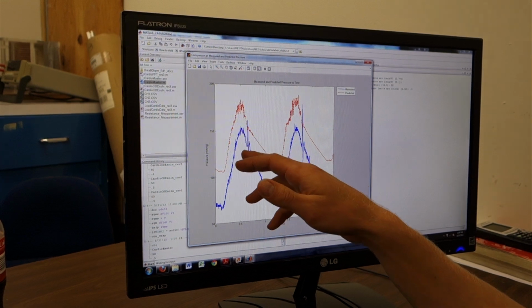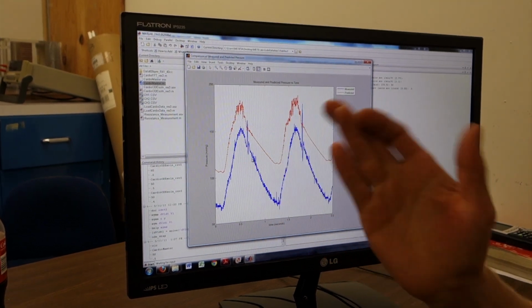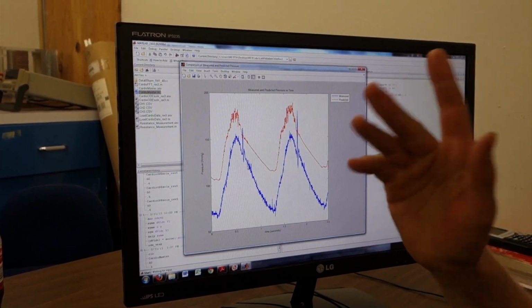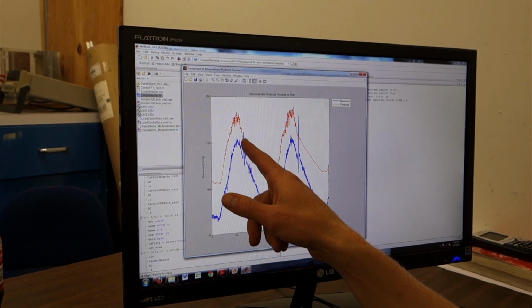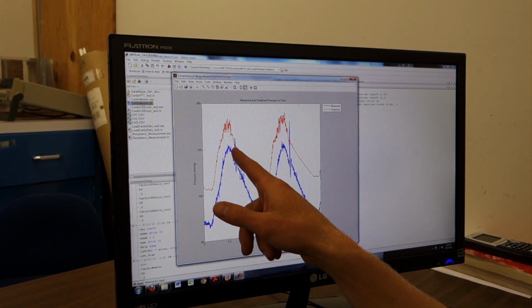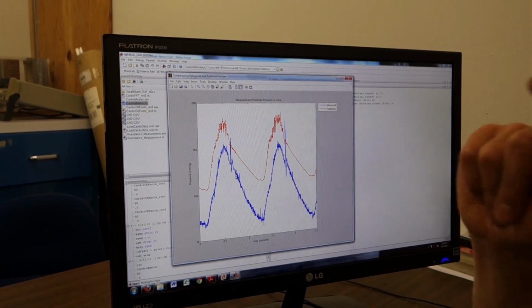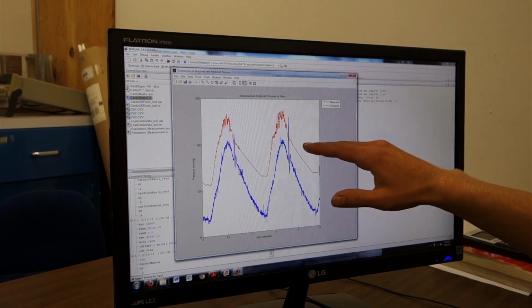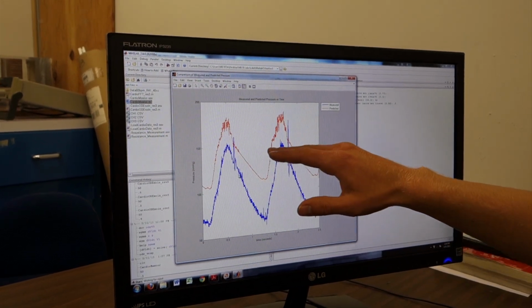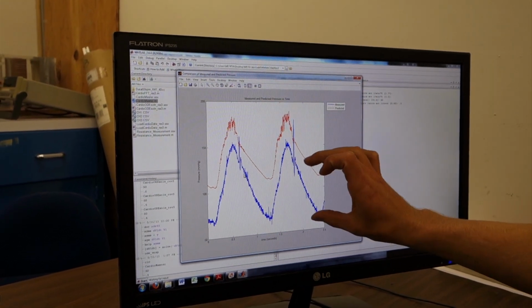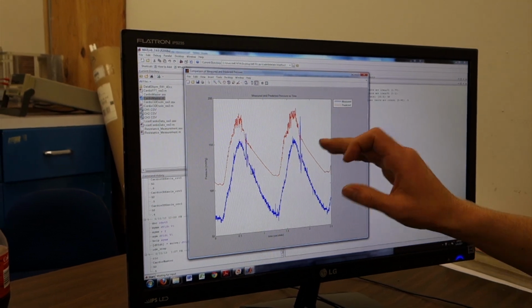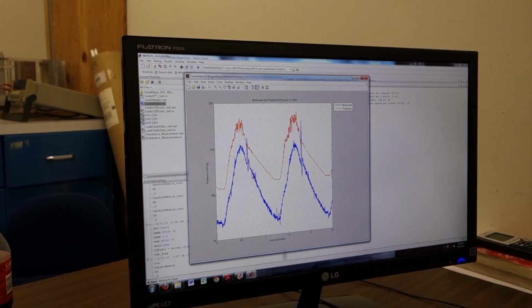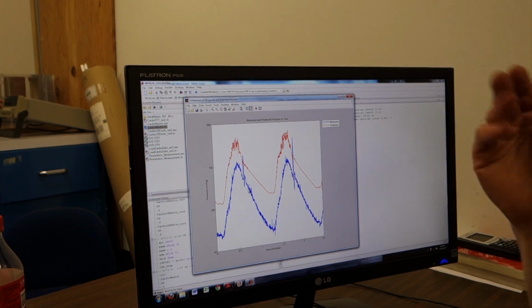There's a high pressure region when the flow is very slow, because we know from Bernoulli's that as the velocity goes down, P goes up. And indeed, we're modeling that in our modeled data with this little notch right there. But we do notice that the mean value of our pressure signal is higher than it should be. So something is wrong with our R1, with our resistance and capacitances.